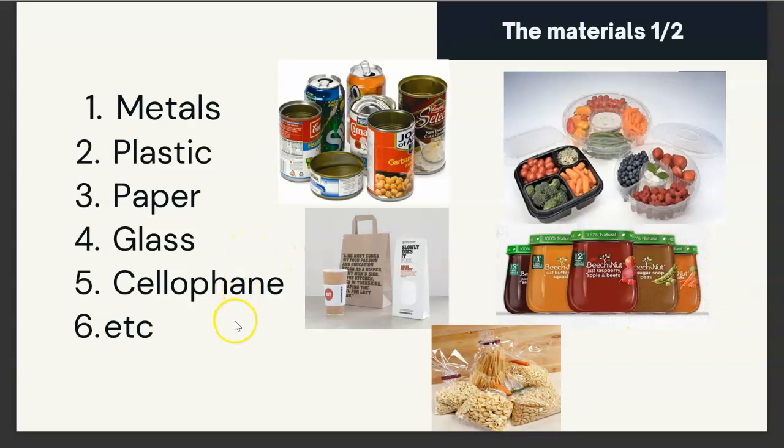And the fifth one is cellophane. It is very lightweight and advantageous in terms of biodegradability. Since it is derived from cellulose, it is also a good moisture barrier. However, the disadvantages are that it has a poor oxygen barrier, is relatively expensive, and is not as versatile as synthetic plastics. However, I think with the latest research and development, they have enhanced the barrier properties while maintaining the biodegradability.